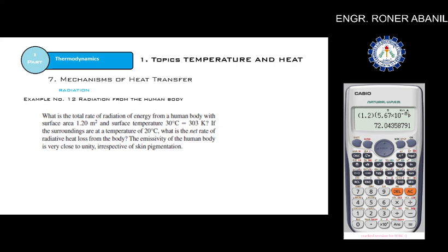A body that is a good absorber must also be a good emitter. An ideal radiator with an emissivity of unity is also an ideal absorber, absorbing all the radiation that strikes it. Such an ideal surface is called an ideal black body, or simply a black body. Conversely, an ideal reflector, which absorbs no radiation at all, is also a very ineffective radiator.